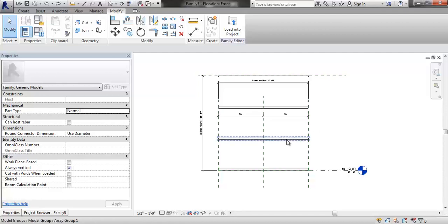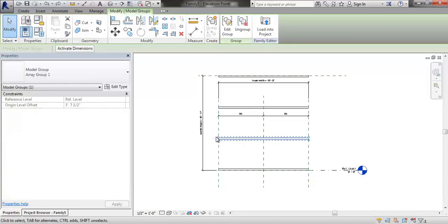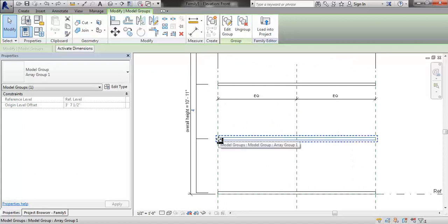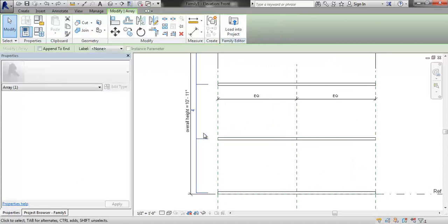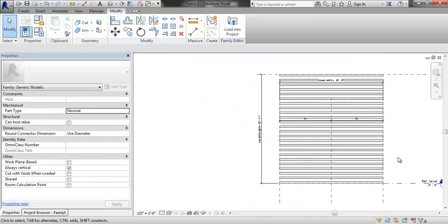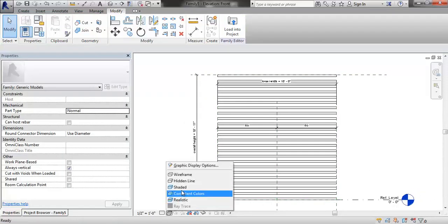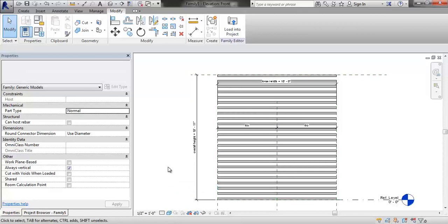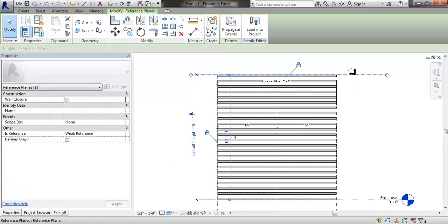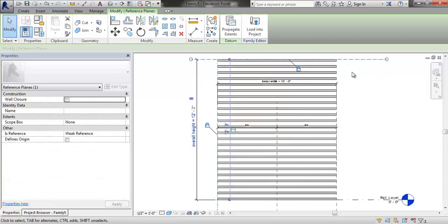So we'll go ahead and take my louver. If I hover over it, it's kind of hard. I still have a problem. I've got to zoom in and select. So there, I select my numbered arrayed system. I can add a parameter called number of louvers to that one. Bam diggity. Last part. Turn on shaded view so I can see it. Now I want to set up a logic so that as I change the height, it adds more louvers to my system.